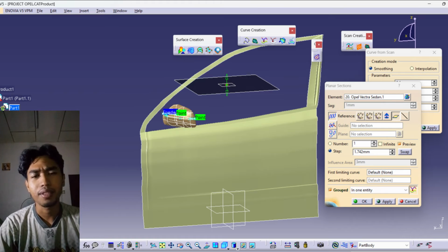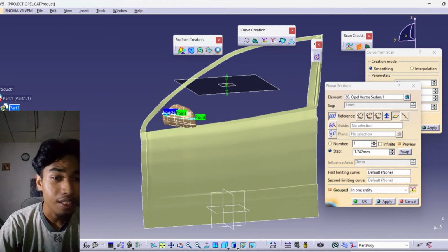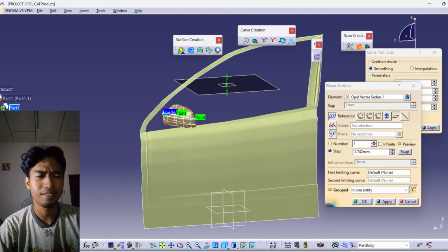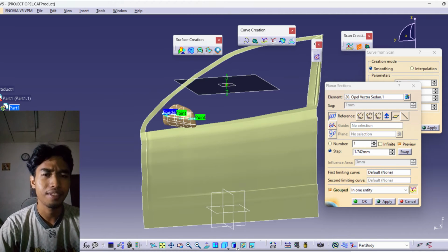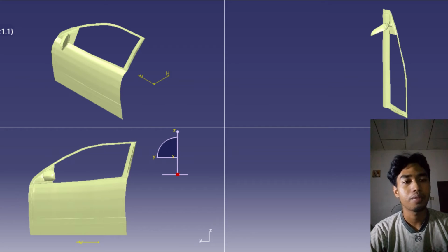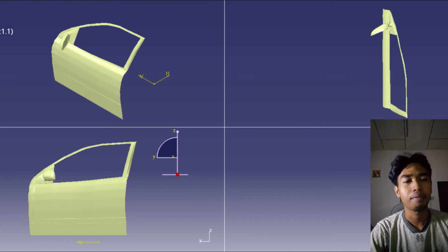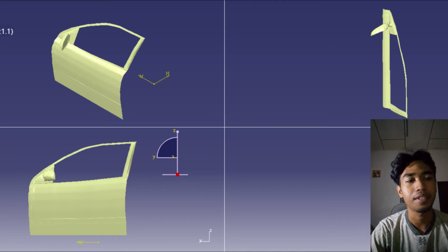For the side mirror parts, it's a bit difficult because they have so many hidden surfaces, so I create it slowly and patiently. When I'm done, I use the multi-section surface for the 3 parts of the wireframe that I applied with curve on mesh and multi-section surface.